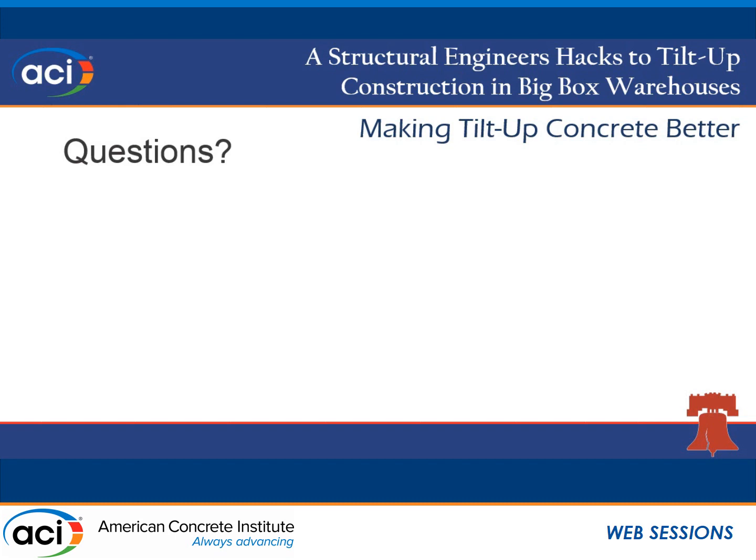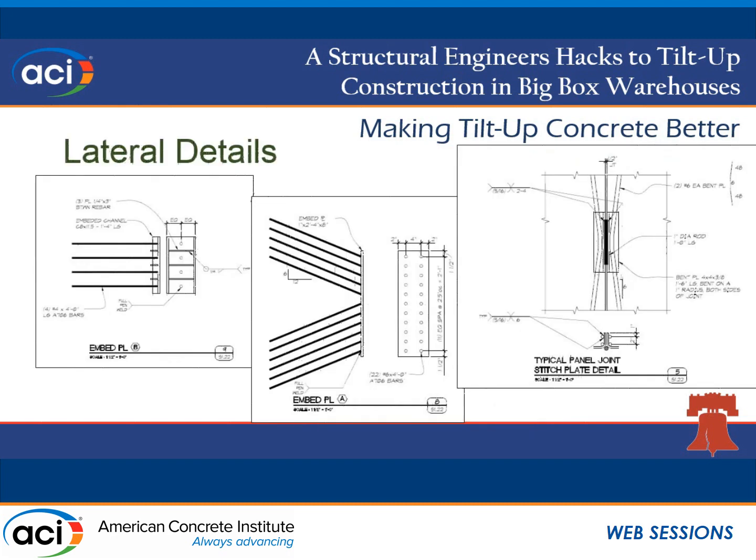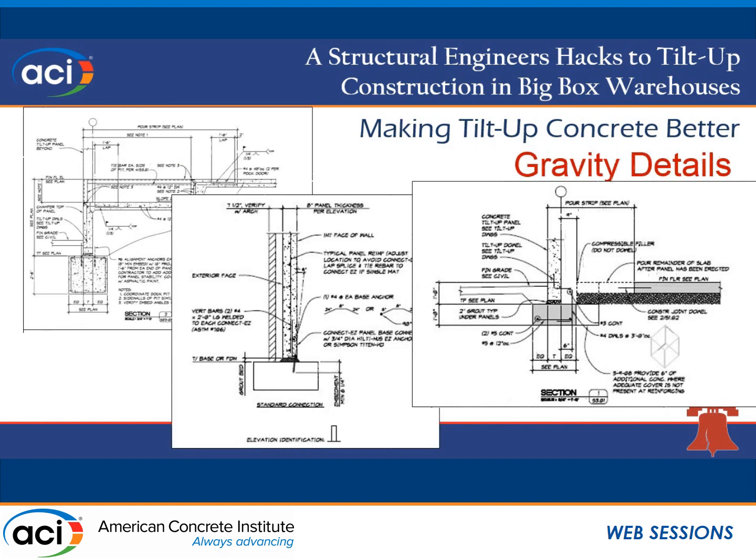Yeah, so usually what I specify would be, let's see if it shows up on the detail. Kind of hard to read, but essentially you call out for 2 to 4 minimum connections per panel, and then a 30 to 50 foot detailed area rebar. So you got the pour back where the dock leveler goes, and then that gets tied, usually actually welded, to a piece of bar that goes back in the slab. Under typical conditions, 20 to 30 feet of slab is enough to drag that load out of.